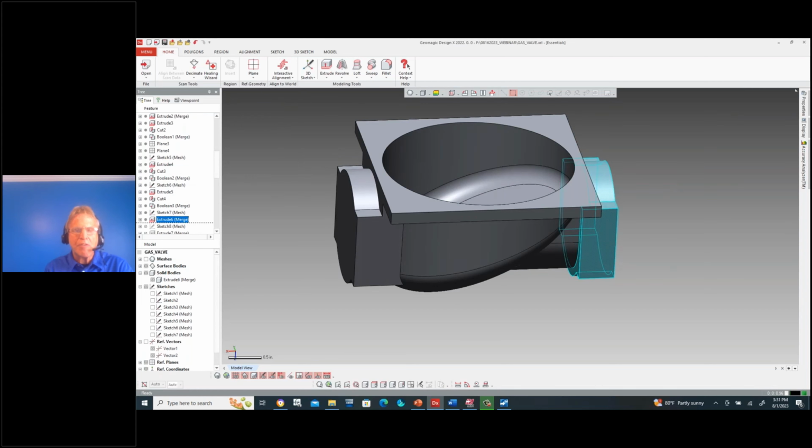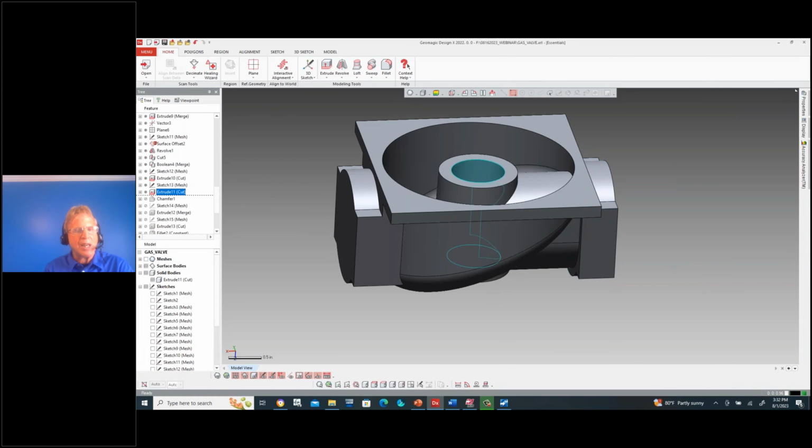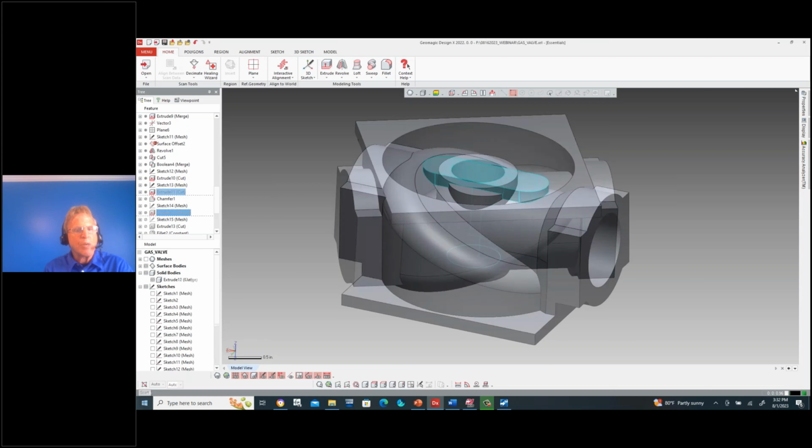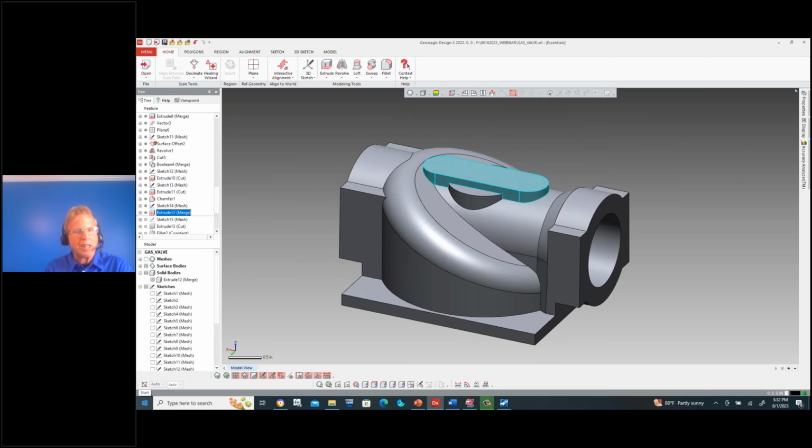So continuing forward, we have some simple basic extrusions that we've added to the outside of this valve. And then we added these internal features, which are really very basic cylindrical rotation features and holes. We've flipped the model over, and we'll go ahead and add that boss base, I should say, up on the top of the piece. We take the base flange here of the cylinder, and we're filleting those radii. Then we're going to add some tooling tabs on the tops, and then we're going to add some tooling holes that are going to mount this gas fixture down.